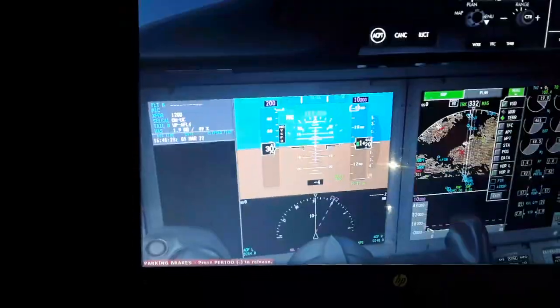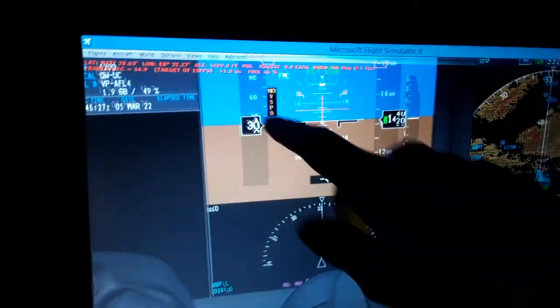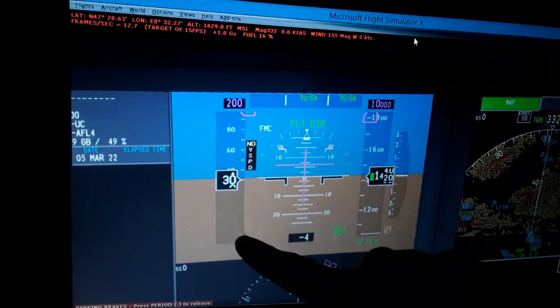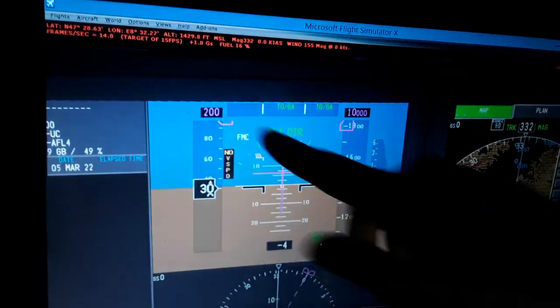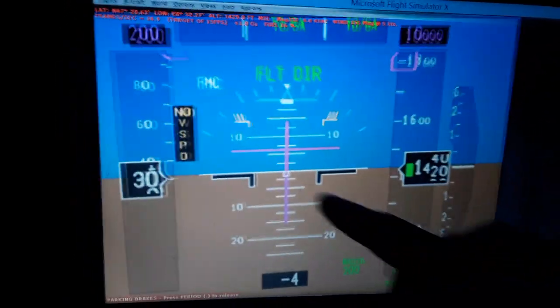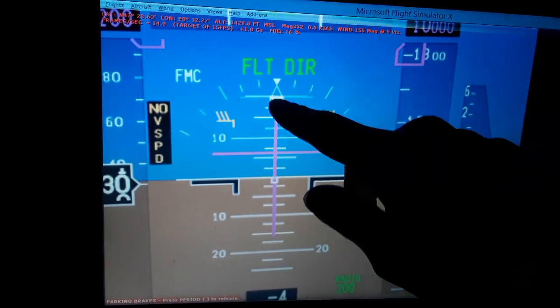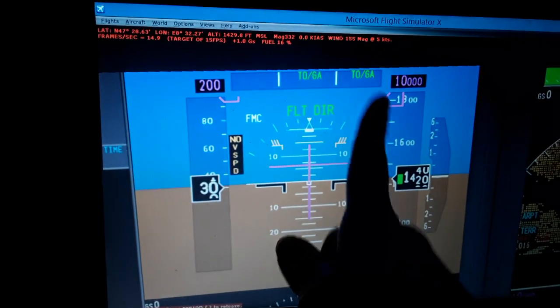We have the airspeed indicator, as you can see. We need to monitor the airspeed as we fly. It needs to be always higher than the stall speed. You're gonna see a yellow and red indication below the airspeed. Also flaps and never exceed speed. You can see the pitch ladders here in degrees: 2.5, 5, 7.5, 10, 12.5, 15, 17.5, 20, for pitch up or pitch down, the bank angle also as we fly.